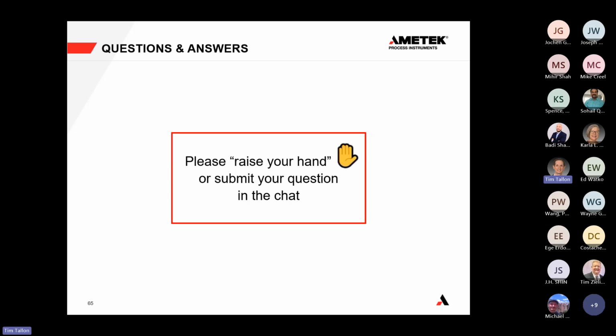So the change in control logic. One of the things that API 556 recommends is having certain interlocks for monitoring for combustibles. They certainly have the low oxygen interlock, but there are two additional interlocks that they recommend per API 556. One is the high combustible interlock, which is around 500 parts per million.